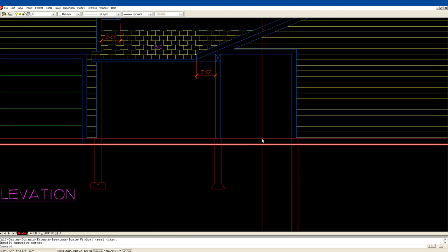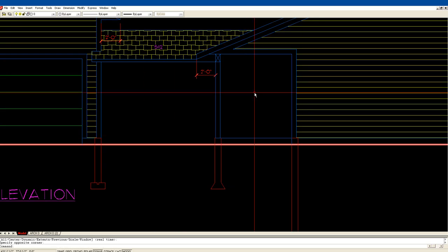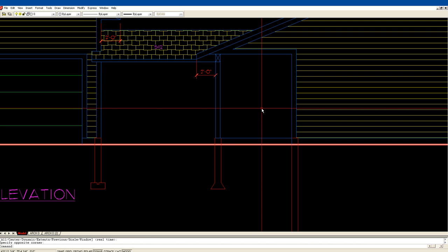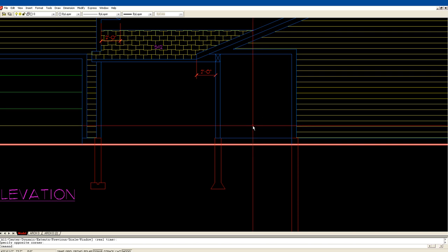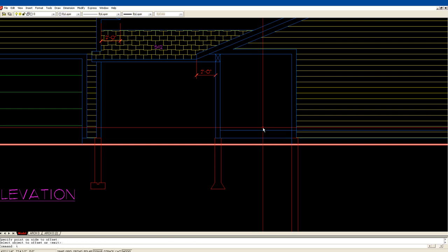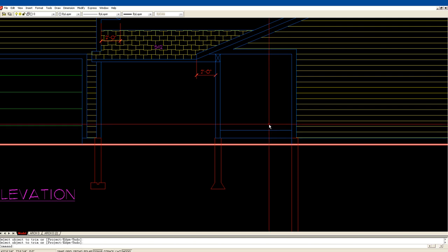Okay, so we're going to start developing the other elevations. There's just one thing I noticed here. This is the deck area in here, and that's this line right here. This blue line is top of concrete. We're going to offset 10 inches for the floor joist so we can bring this deck up to, I'm just going to trim it off here, up to the floor height.